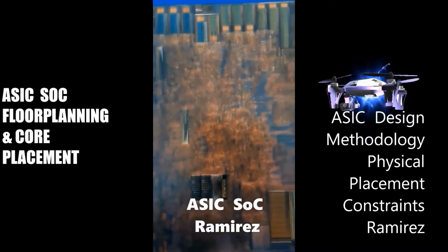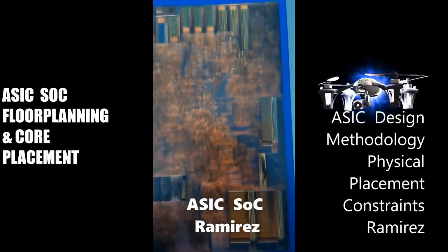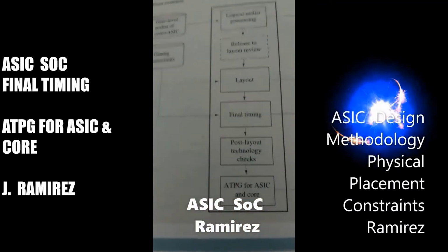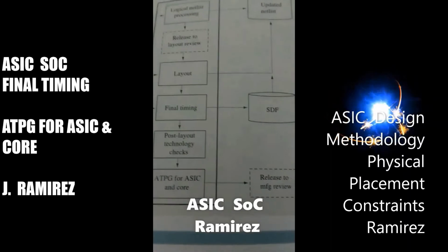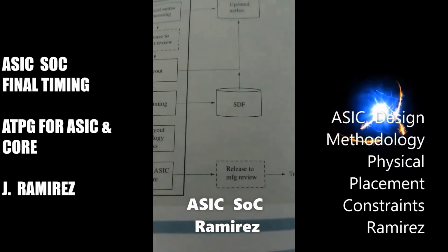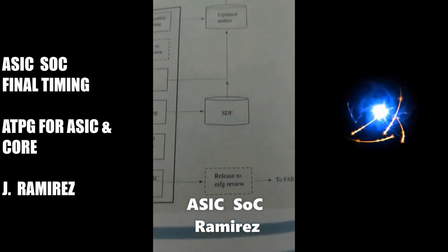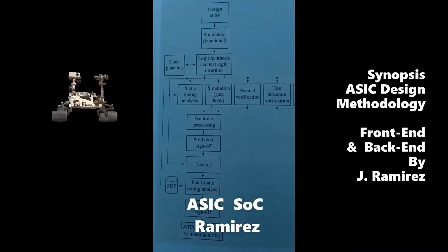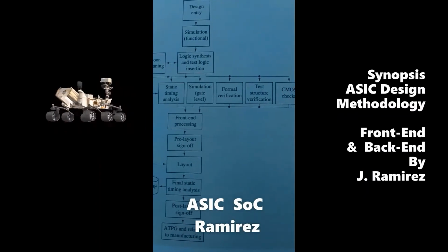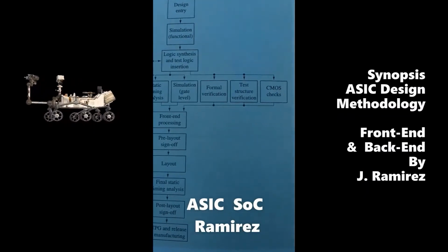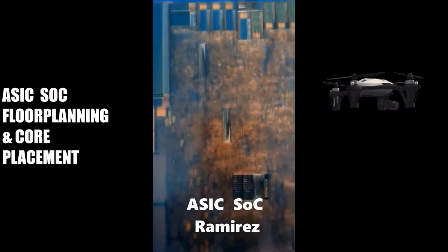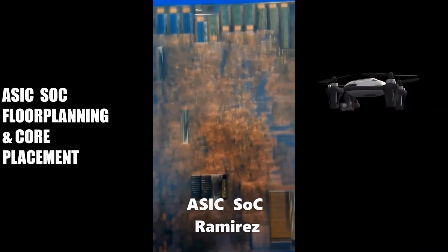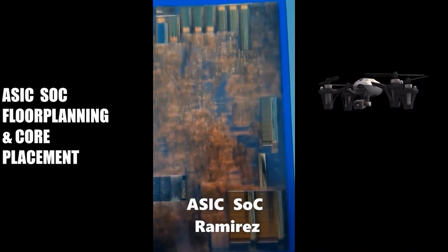Placement constraints. The area planner analyzes the distribution of the shapes and sizes of the library cells that take place in each macro cell, determines an optimal periodicity of circuit rows or columns, and creates the placement structures based on each macro cell.